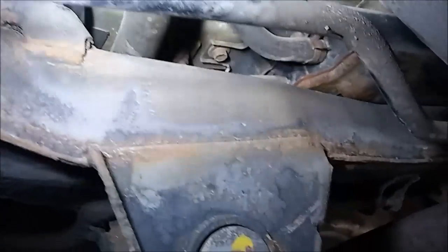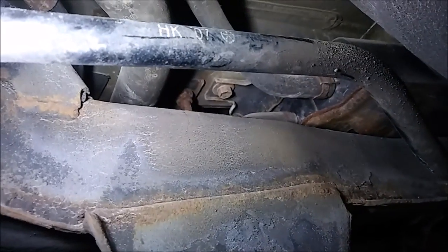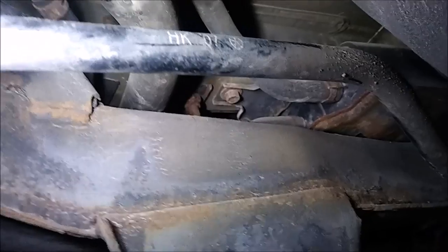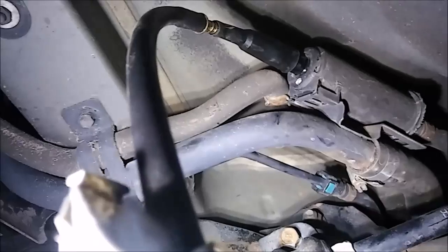Alright guys, I was finally able to get smoke into this system. And I'm not sure if you guys are going to be able to see it, where it's coming from. This was the connection I used. I'm just adapted into the end of this inline vent for the canister vent valve. If we go way up here, the leak appears to be coming from the canister.